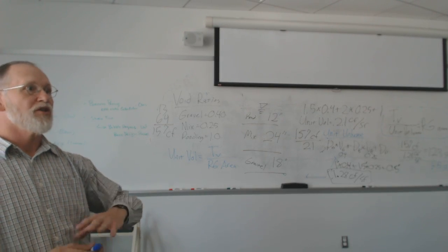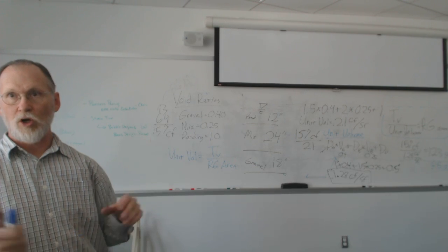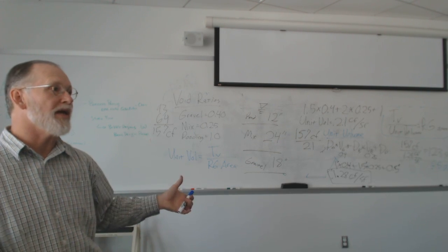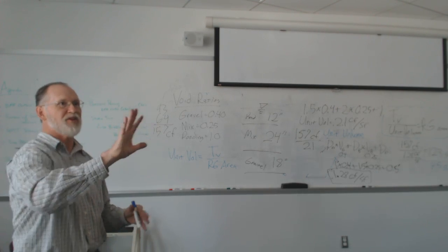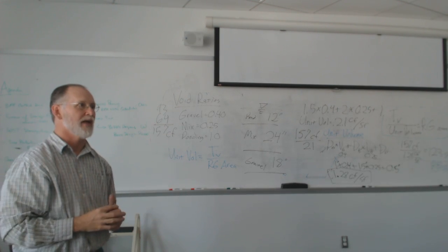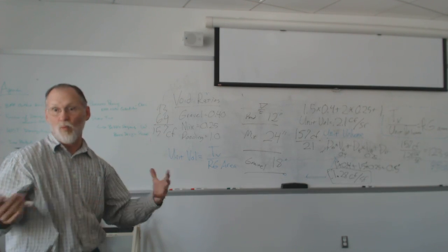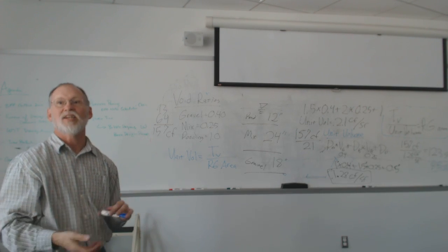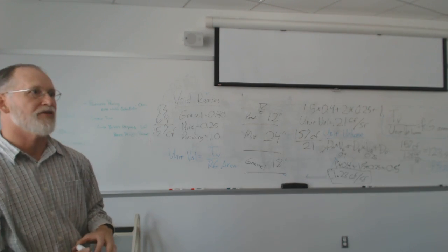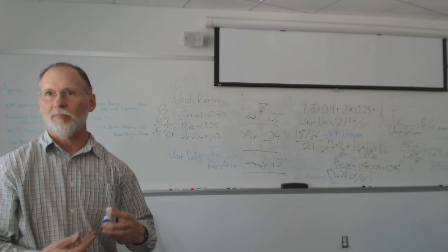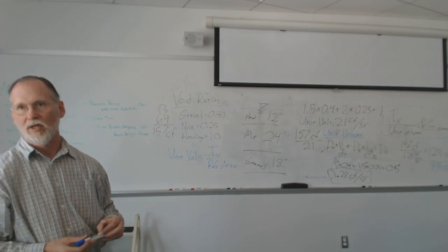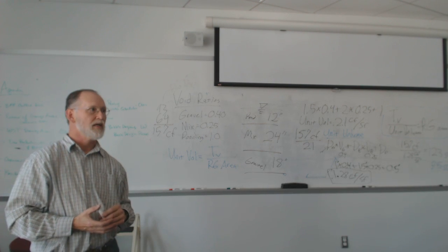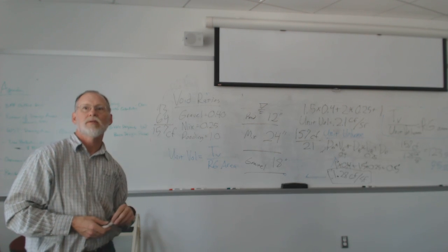It is possible to drastically oversize these. If you get too big, depending on your design, plants at the far end of a really large rain garden may not get enough water, and that soil is really well drained, so you can run into long-term maintenance issues if you get carried away with sizing. But you've got some latitude here.